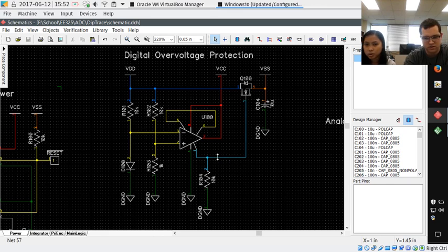We thought about putting a diode in the circuit, but since the CMOS circuit draws a little current, we were concerned that due to the nature of the load, the diode would cause an unwanted reset. Basically, if there's no current flowing through the diode, it will go into cutoff and turn off the digital voltage, which could cause the power on reset to activate when we didn't actually want it to.